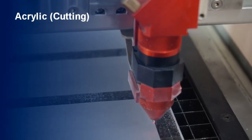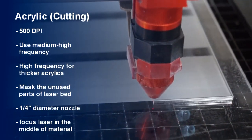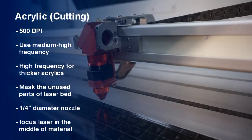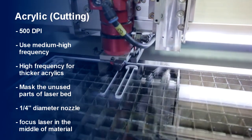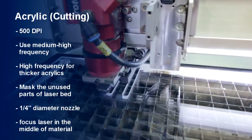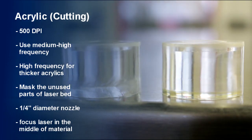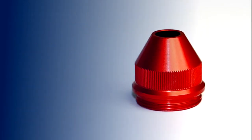Tips for cutting acrylic. Use 500 dpi. When cutting acrylic, use medium to high frequency levels. Increase the frequency for thicker acrylic to create a nice flame-polished edge. Mask the bed to increase draw and reduce flaming. Use a 1/4 inch diameter nozzle. Focus the laser head 1 mm to 2 mm into the material for every 10 mm of material thickness. Use the 1/4 inch diameter nozzle.